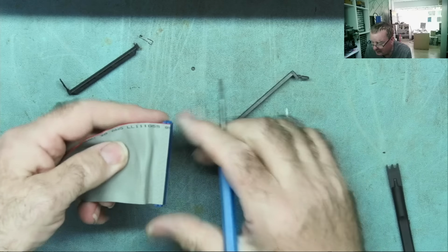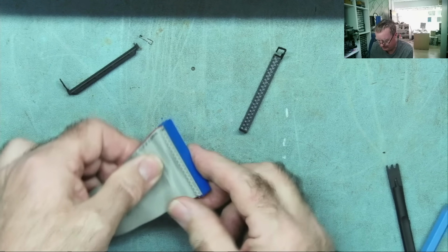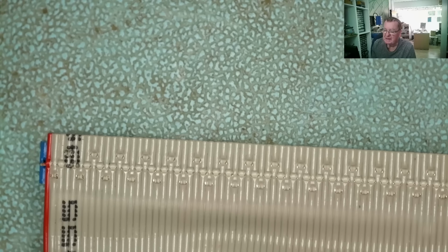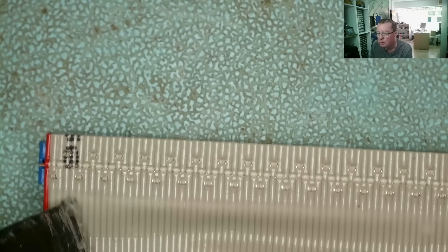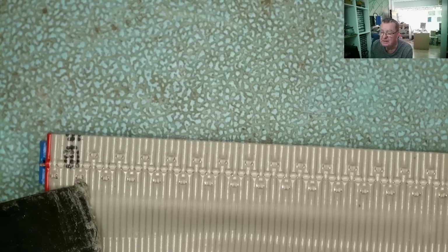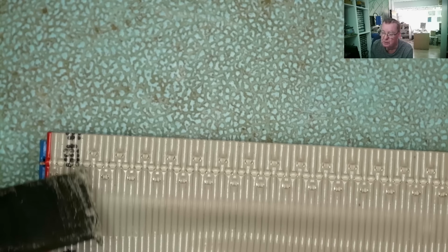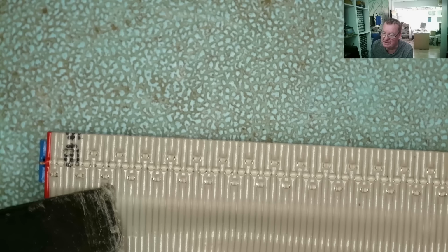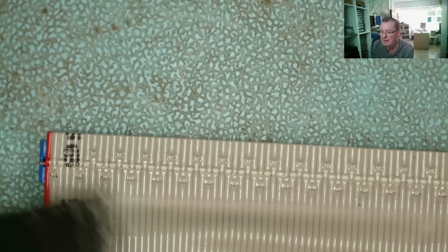Okay, and then we actually have the insulation displacement itself. Here we can see that each pin in the connector has a little tuning fork type thing, okay? You can see there. It has two prongs and a gap in between. When you clamp this together, and you need a proper clamp to do this really, but you can do it with a large pair of pliers if you're careful, yeah?